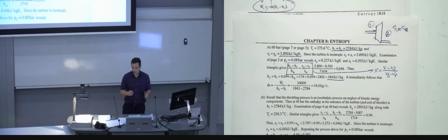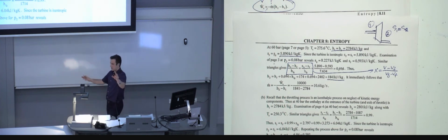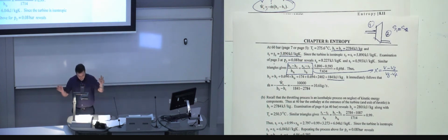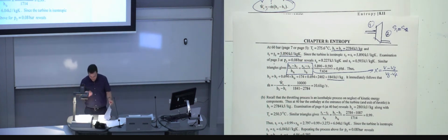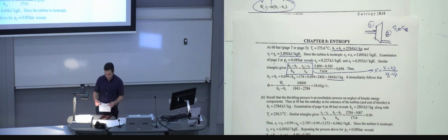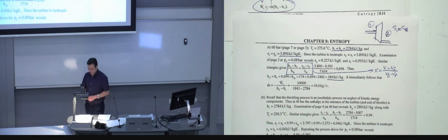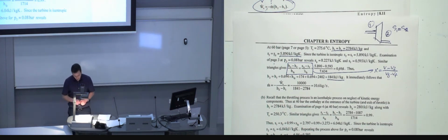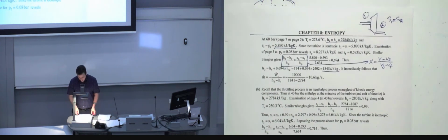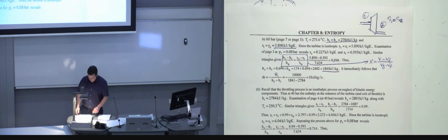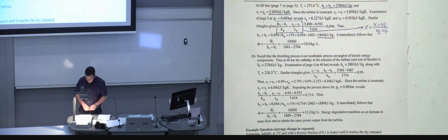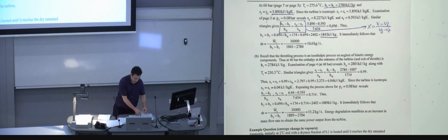So what we did, for the two pressures that we had before and after, was find Sg and Sf and Hf and Hg, and from those, you could find the enthalpy in both cases, and therefore, as a result, the mass flow rate. Now, I have to go through this quickly. The fact that we now have a throttle makes the equations slightly complicated, but still it's not that difficult. It's the same principle.